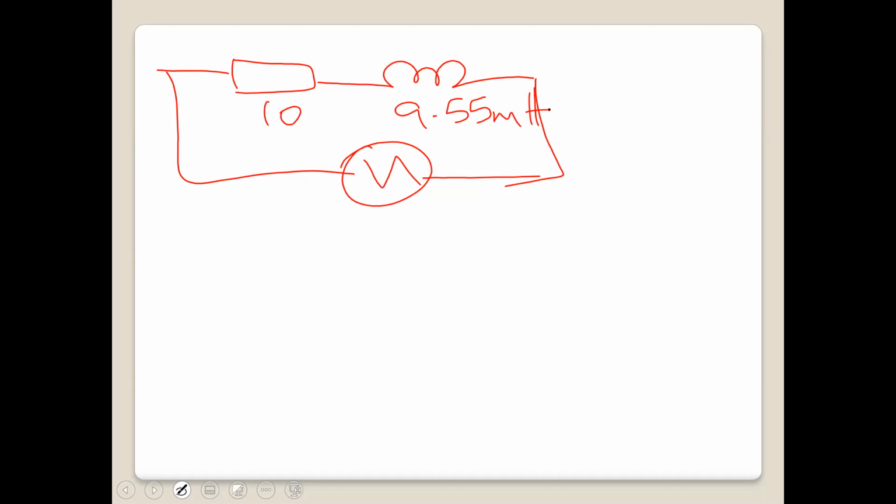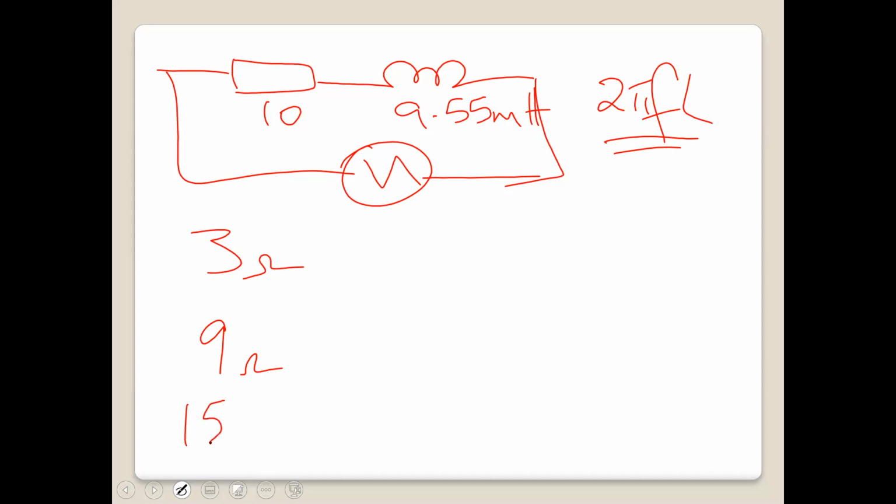For the fifth, it was 250, etc. Now, you would note, however, that if the fundamental XL was 3, because you are dealing with inductive reactance, and we have here 2 pi FL, then for the third, it will just be 3 times 3, which would be 9. For the fifth, it will be 5 times 3, which will be 15. If I want the 10th harmonic, then it will be 10 times 3, which would be 30, and so on. So you don't really have to go back and recalculate if you bear this in mind.